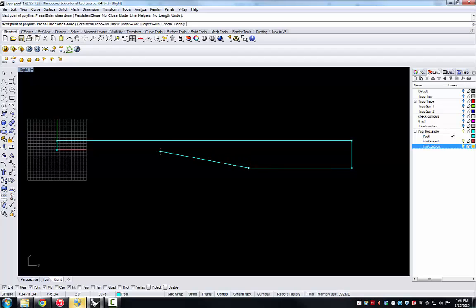And now I'm going to do an angled line where I'm going to use a different input, which will be the at symbol. And that means that I'm going to go from this point to a relative point, which will be 35 feet negative in the x, so minus 35 in the x. You don't have to type x, just at minus 35, comma, 6, which is going to bring us back to the location here, which is 35 feet back toward the origin and 6 feet up toward the origin.